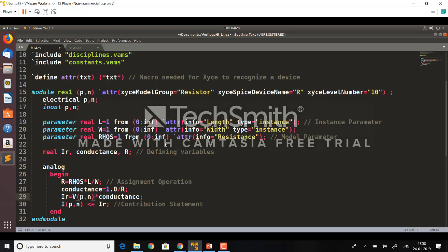Okay, they measure the transistor. They start IC-CAP. It's exactly what they do. They measure the transistor. They use BSIM3 or BSIM4, I guess TSMC uses BSIM4, and then they use IC-CAP to fit all that data. When you fit all that data, you get certain values for parameters.